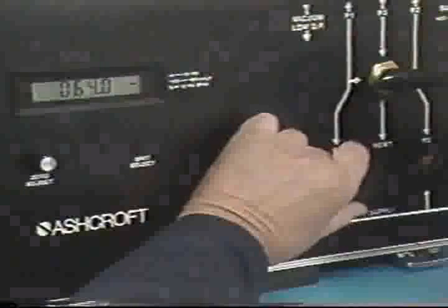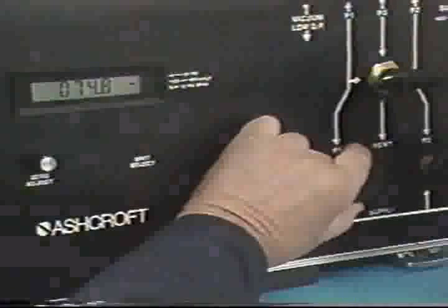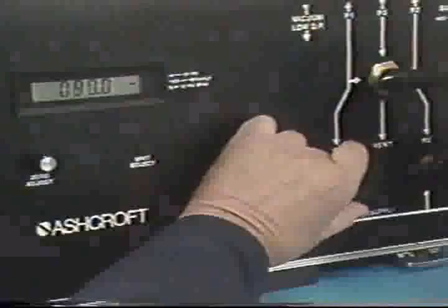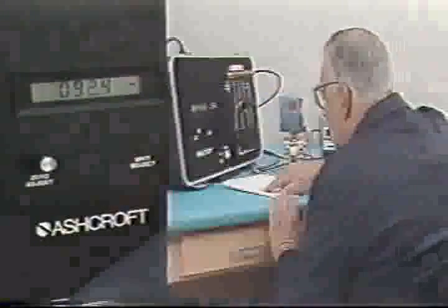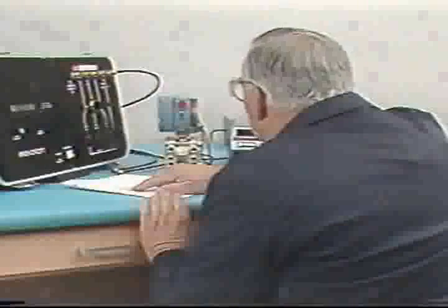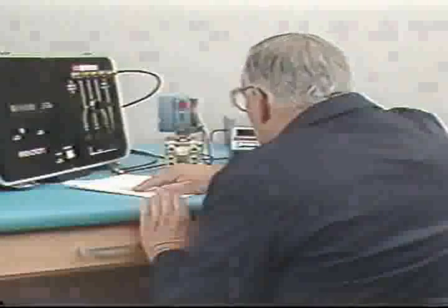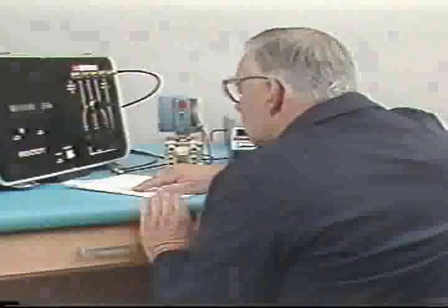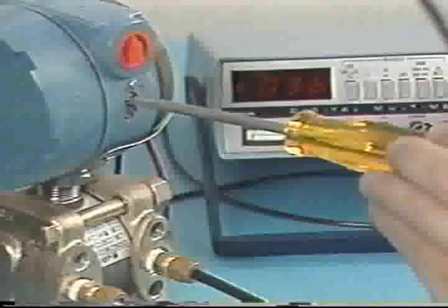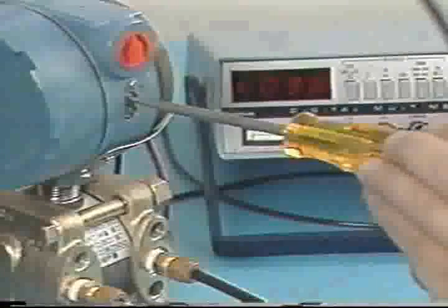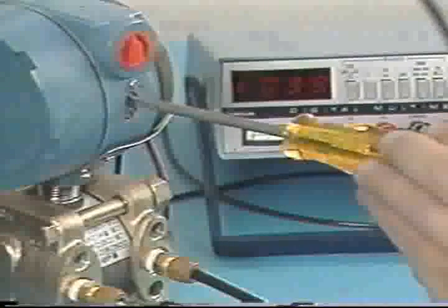Calibrating a differential pressure transmitter that's used in hydrostatic level sensing requires a few special calculations. To determine the appropriate test points, you'll use a span value that's been adjusted for specific gravity. And with some applications, you'll determine the additional hydrostatic pressure that's applied to the transmitter's low side. Sometimes the zero will require elevation or suppression by a calculated value.